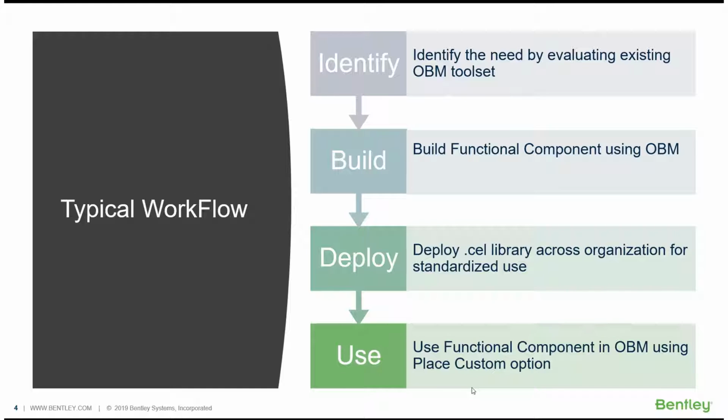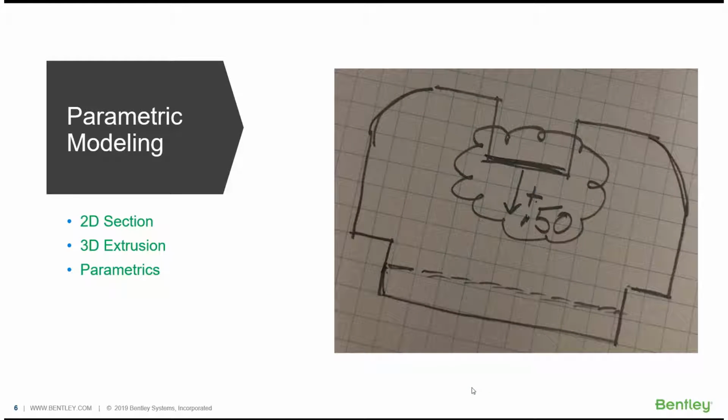So how do you start thinking about how we're going to create this? I want to do it parametric, so maybe think about which dimension, for example, is going to change. If I want to modify this dimension up and down, what happens with these lines? Are they going to remain the same? If this goes down, should this line move? You have to think about how these major or minor changes you make in your structure will affect the rest of the elements.